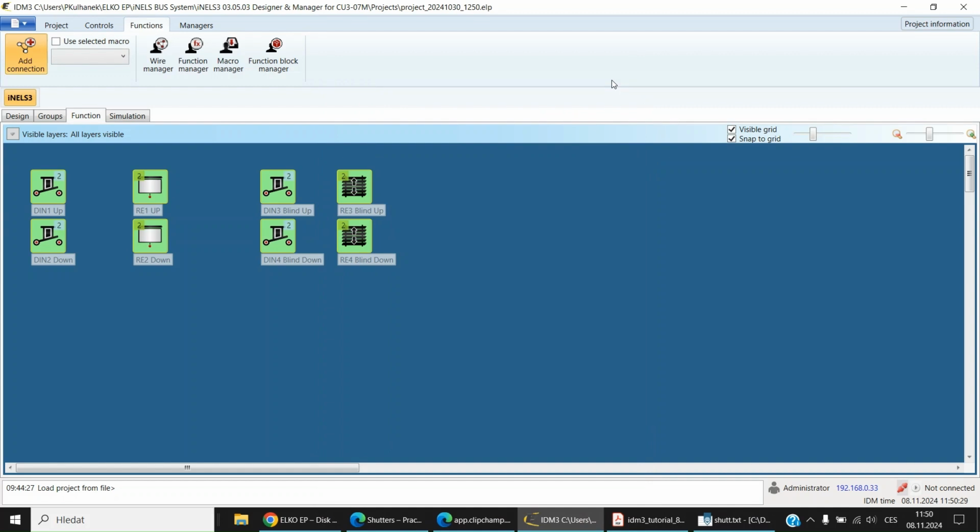Any project created in IDM, no matter whether a new project or a default template, contains a function block template called shutter control, which contains a complete logic including shutter or blind pulling up and down, and as well slat tilting up and down. Both actions use the corresponding functions with predefined times, so we will also show where to edit your own times after creating a copy of the function block.